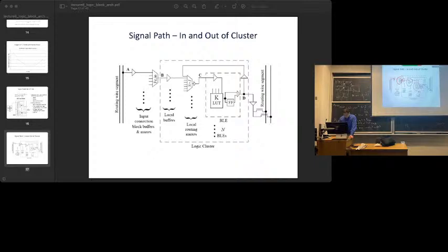And then you can pick one of those two signals to come out, and there's a buffer here driving you back to the local routing, and another buffer here driving you out to the general routing. Overall, it's a pretty reasonable electrical design. This one buffer here is the one that probably should be left out, and future studies did leave that one out. I think there's a question.